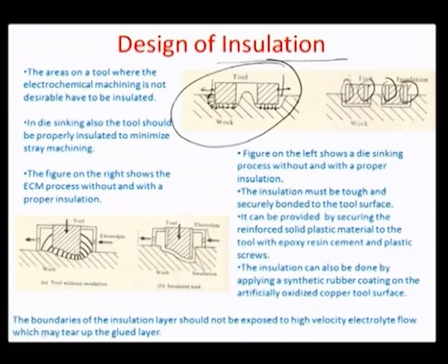which would typically mean that the current density vector, which is responsible for all the electrochemical movement, is only confined to this portion of the surface. The remaining portion is insulated now, and so there is no field loss as such from this portion of the surface onto the other portion of the workpiece here, and that ensures that the size of the hole that was intended while doing, let us say, the drilling operation with ECM is met.